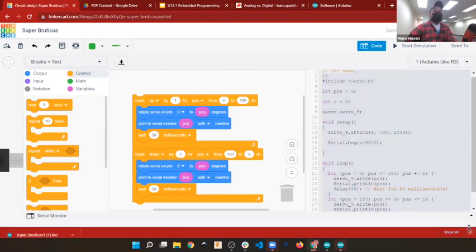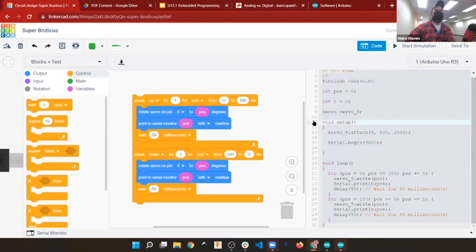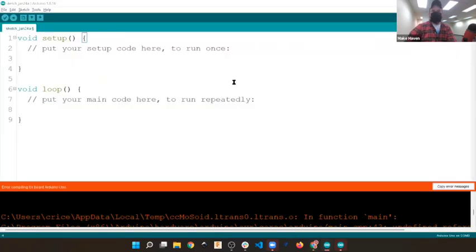So you can either do that, or you can directly download the program, and then you can use it from there. So the bare minimum is that you need to have a void setup, which is right here, and it goes from lines 11 to 17 in this program, and a void loop, and here it goes from 19 to 31. And so that is totally the minimum that it takes to make it run. You can get to it lots of different ways, but that's what it takes just to get started.